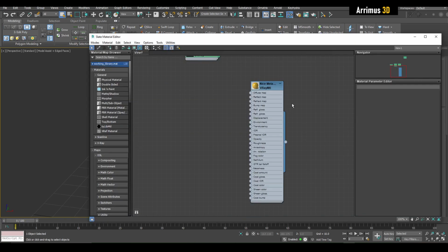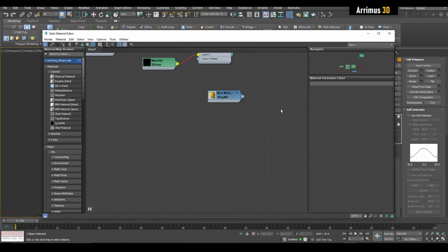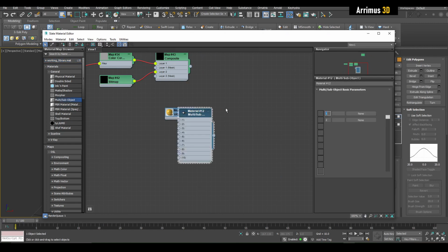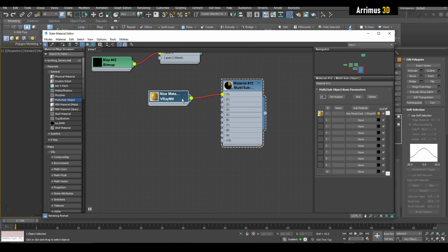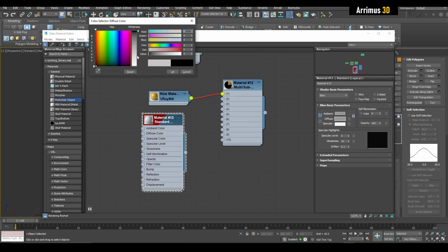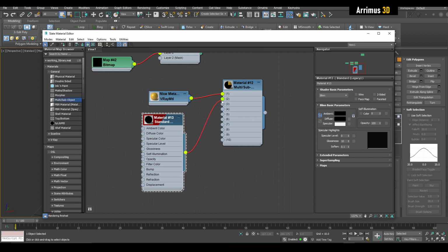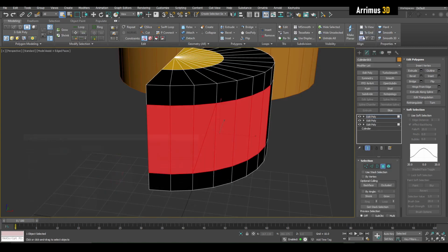Now, this video series will only cover the modeling and designing and not the material or texturing or lighting, but I just want to show you how you can, for example, create a multi-sub object right here. All right, I'm just going to plug this V-Ray material into one, but if you don't have V-Ray, you can simply use a standard right here. So I'm going to make this one, this is going to represent the window for now. So I'm going to plug this into 2. We're going to apply these materials. Just remember, 1 is for the yellow, 2 is for the pure black right here.